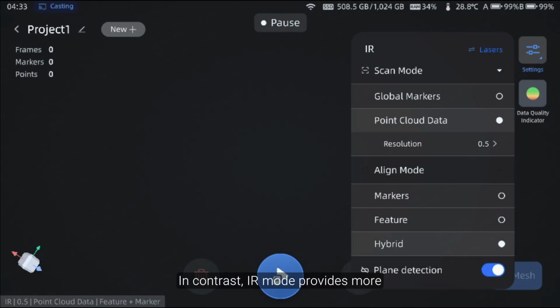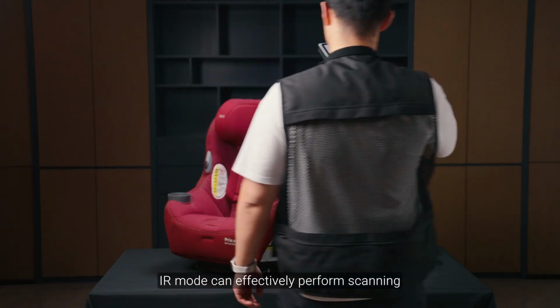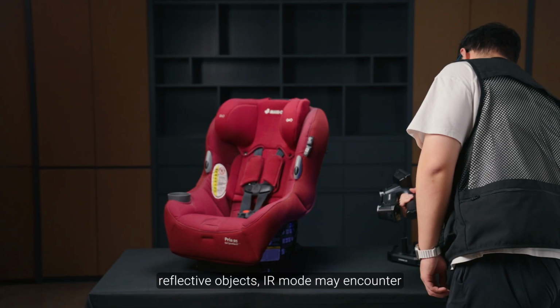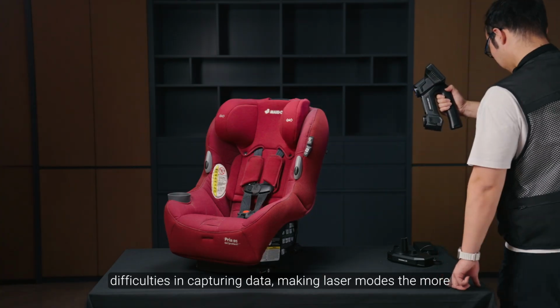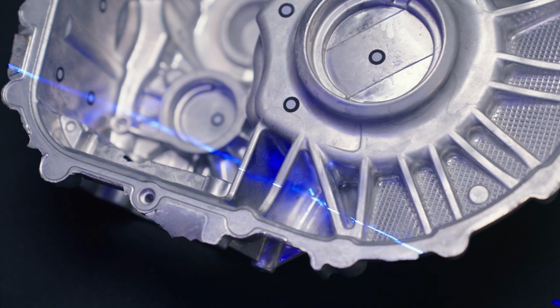In contrast, IR mode provides more flexibility by allowing you to choose between features, markers, or a hybrid approach for alignment. For objects with rich geometric features, IR mode can effectively perform scanning without the use of markers. Nonetheless, when it comes to reflective objects, IR mode may encounter difficulties in capturing data, making laser mode the more suitable choice for this type of materials.